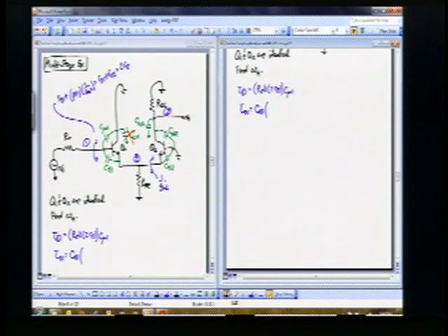Right? And so what I want to be able to do here is just write down that expression, and that's where you've got to kind of memorize this expression right here. Okay, so unfortunately, this is one that has to be memorized. Okay, so I've got an R pi in parallel with RB plus RE. So RB represents not the shunt resistance at this node, right? This is R capital B. So in this nomenclature, R capital B means all the resistance seen looking that way. Not in shunt with that node, but looking out of that node. Okay? And RE likewise, everything looking out that way, and then divided by 1 plus GMRE.